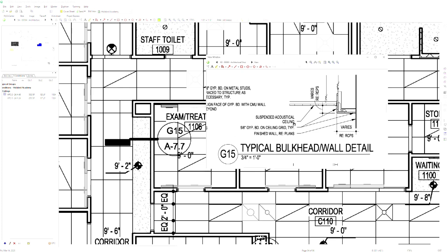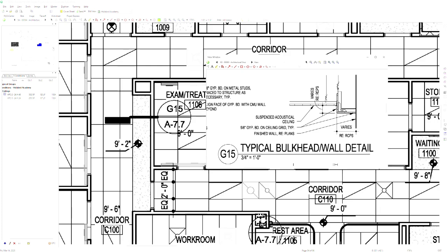All right, so first we see that there are two varying heights here. The corridor appears to be higher than this soffit. The corridor is at 9'6". The soffit is at 9'2". So there's a 4-inch transition. This is your transition right here. This is the 4-inch transition.